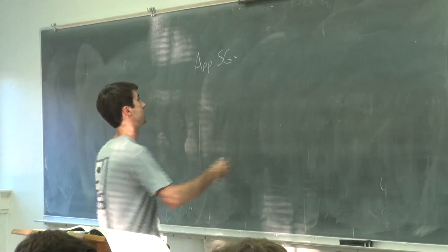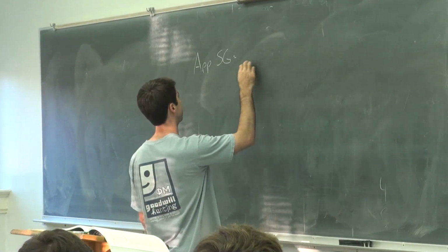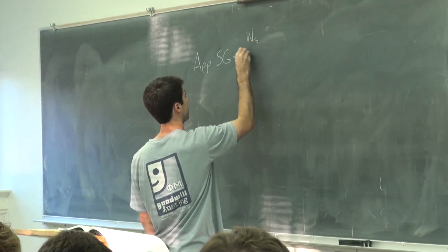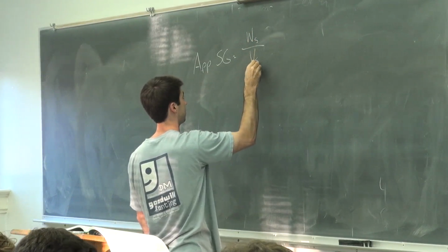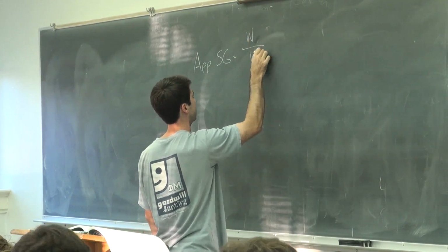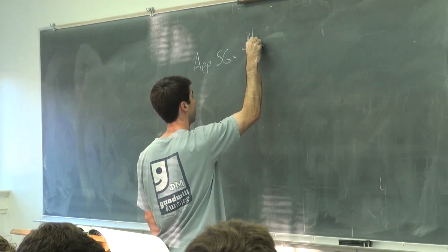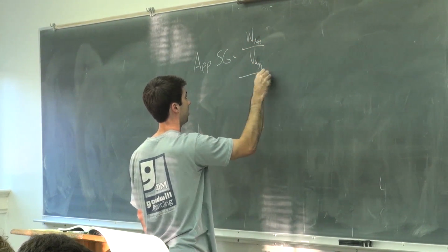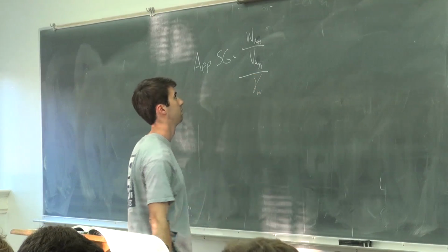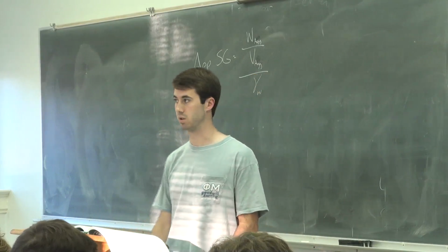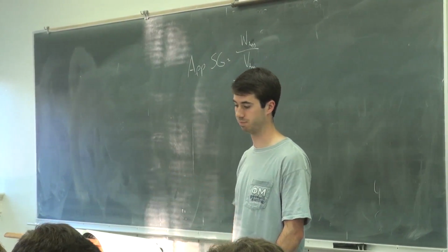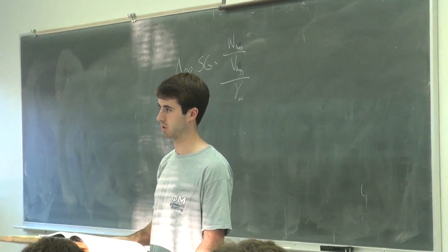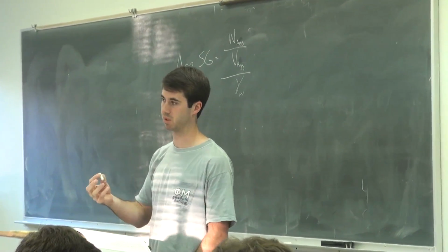No. It doesn't matter because water is not included in this calculation. You've got weight of solids over the volume of the solids. And actually, let's write this in terms of the weight of the aggregate, the volume of the aggregate, over unit weight of water. So you're not including any of the pores.